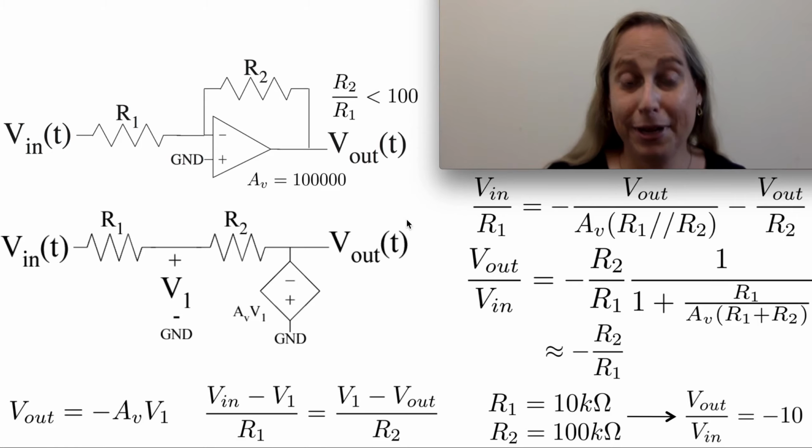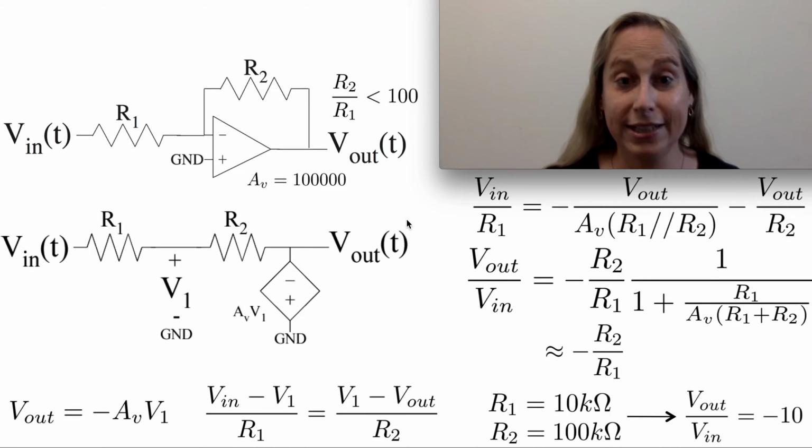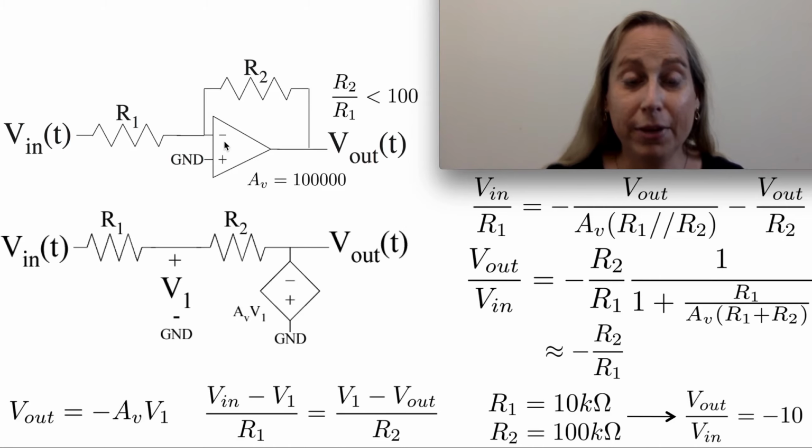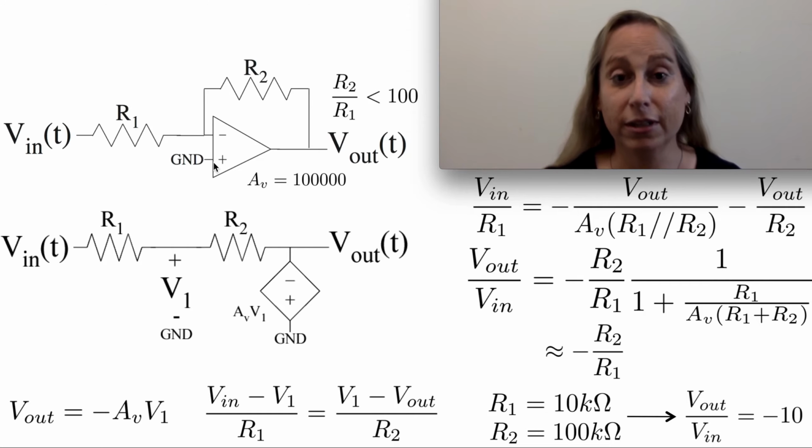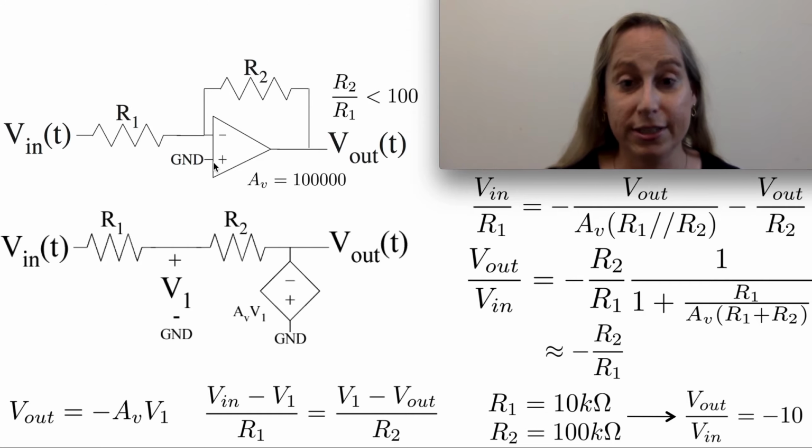I'd like to talk about what you would have for a typical op-amp circuit. In fact, this is a classic inverting amplifier op-amp circuit. But I want to think about this circuit in realizing that it actually is a sort of linear circuit where this effectively describes a voltage-controlled voltage source. And to think about what this looks like also helps you get a sense of what the limits are and what the various trade-offs are when we look at various op-amp circuits